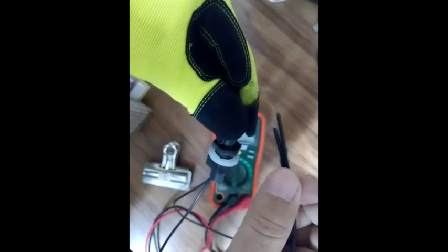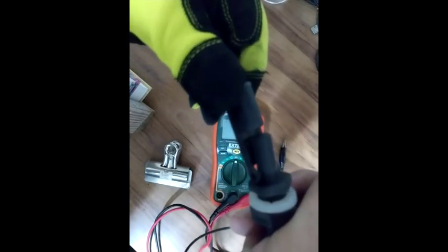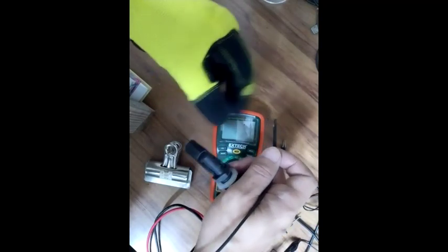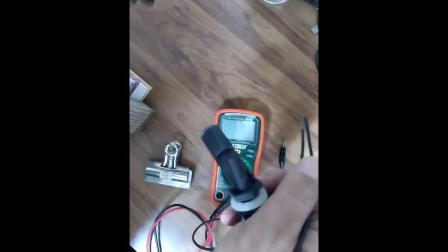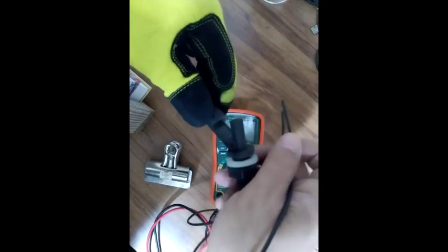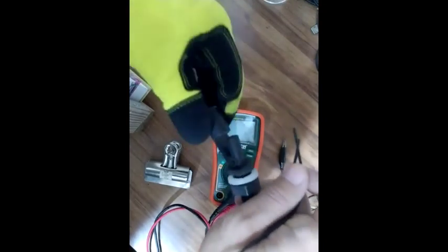Those two terminals will then be used, indicating that there's a short circuit. Depending on whether you install this very high on the vessel, that will be a high level. If you install it low in the vessel, that will be a low level indication. If you install multiple of them within a vessel, then you can have a profile of the liquid content within the vessel. Let's do a quick test here, and see what happens.